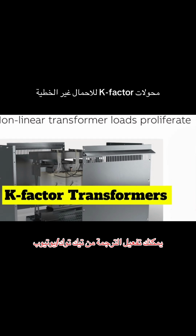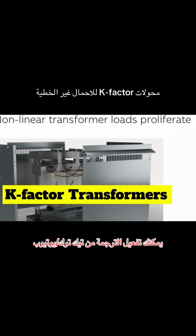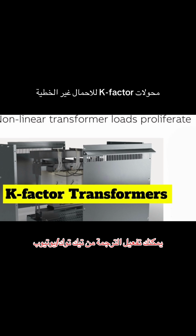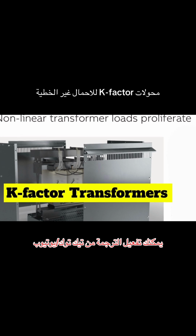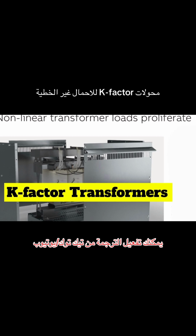Exactly. And that number is the K factor. The paper mentions that this factor can range from 1 to 50. Now, what does that actually mean in the real world when you're picking a transformer? A K factor of 1 basically means the transformer is intended for those clean, smooth 60 hertz loads, the ideal scenario. But as that K factor number goes up, it indicates that the transformer is designed to handle more and more severe harmonic environments.